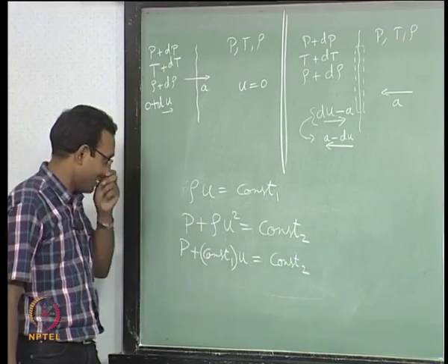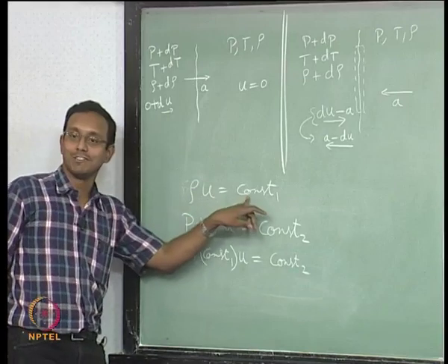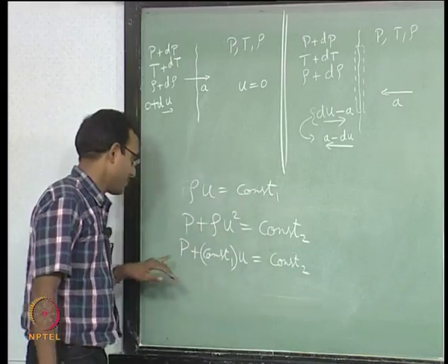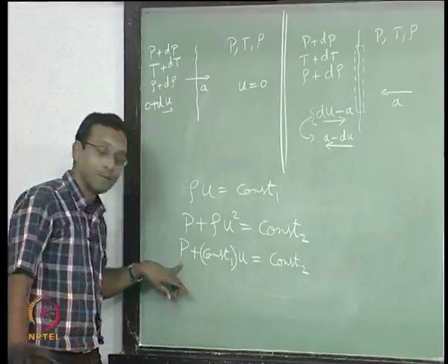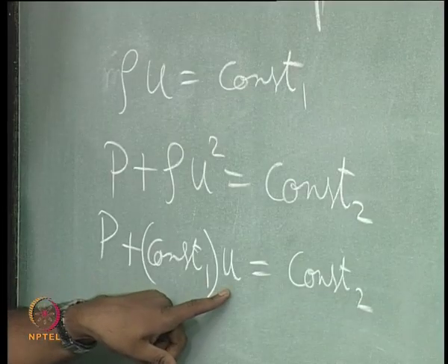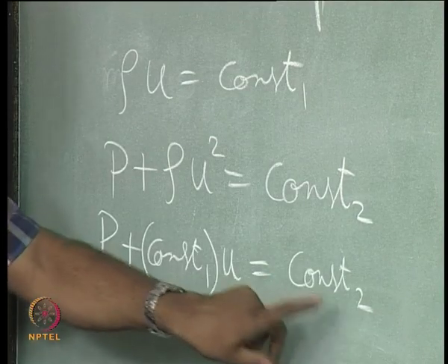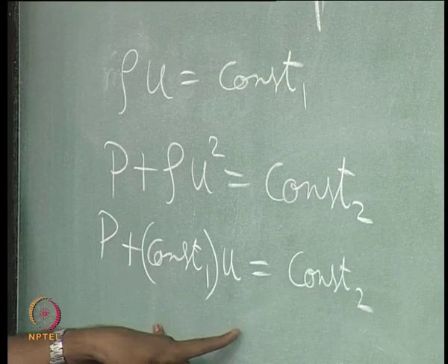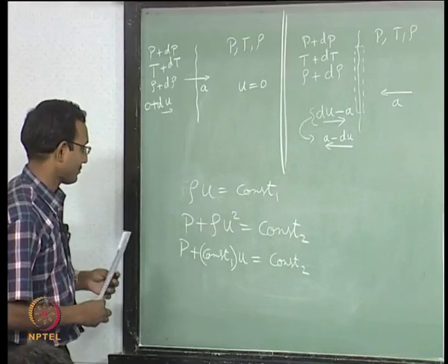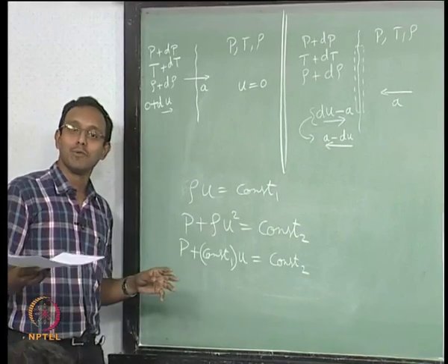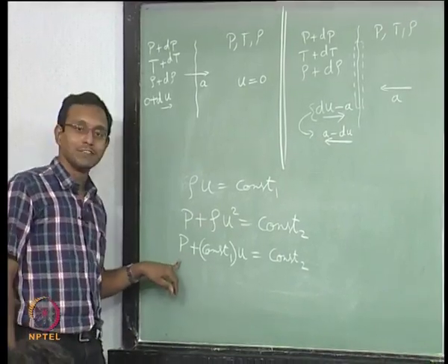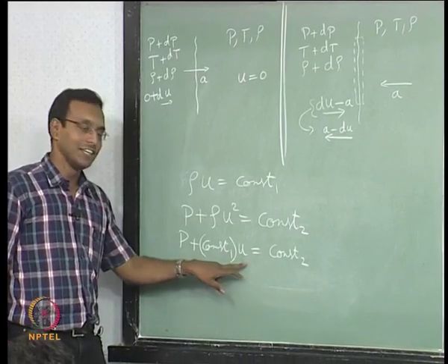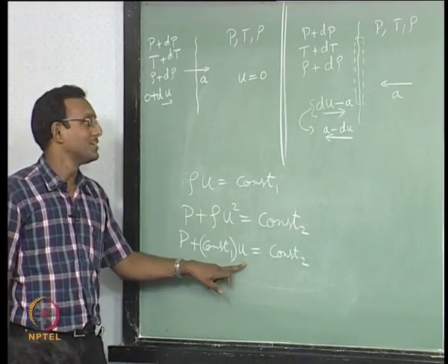Anyways, we will leave that out, we know that mass flow rate is always positive, okay. So I am going to think about this as when pressure increases velocity decreases because it has to maintain the constant. This term increased, this term has to decrease, okay. That is what I have to think about. So I am already giving you a proof saying if it is a compression wave, velocity decreases. Is that what we saw?